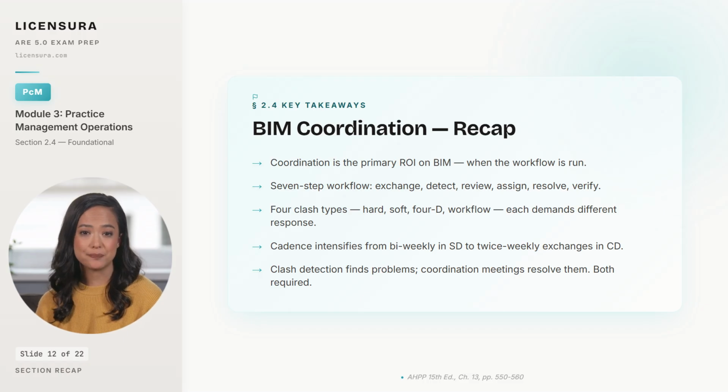5 takeaways on BIM coordination. First, coordination is the primary return on BIM investment, but only when the actual workflow is run. The software alone produces reports, not resolutions. Second, the 7-step workflow: exchange, detect, review, assign, resolve, verify, has a named owner at every step, and missing owners is how clashes survive into the field.